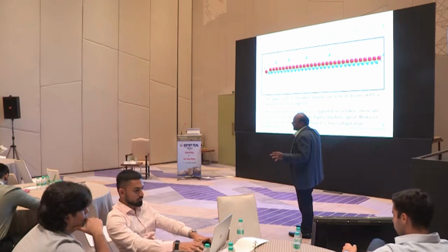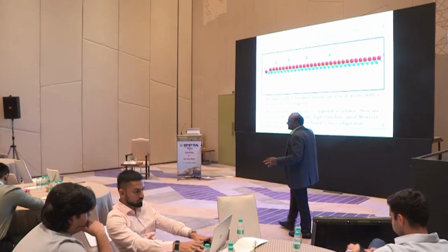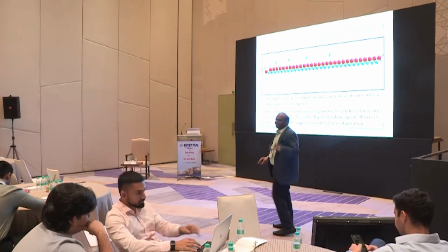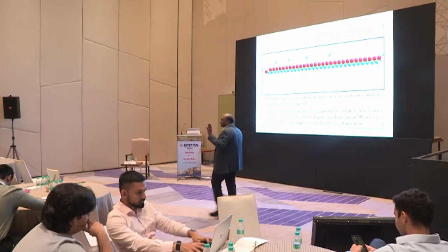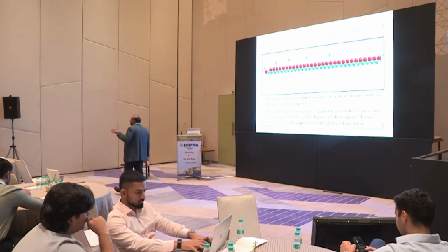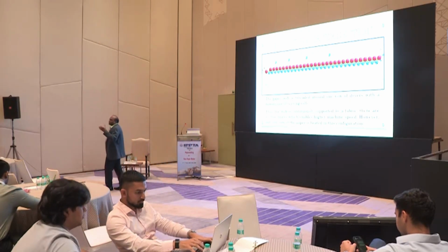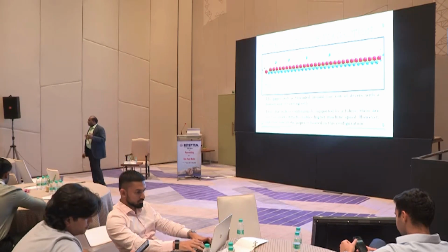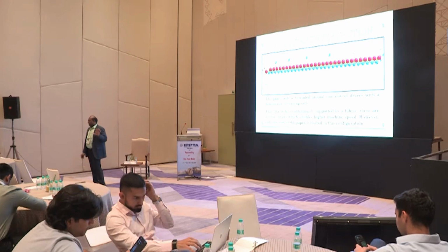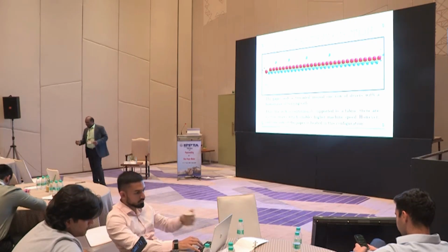Now the support is coming, so we can increase the speed. But here the drying is happening on only one side and the other side of the paper is not dried, and this is not suitable for papers prone to curling like copier paper or coating varieties, since only one side is drying, the paper will curl.